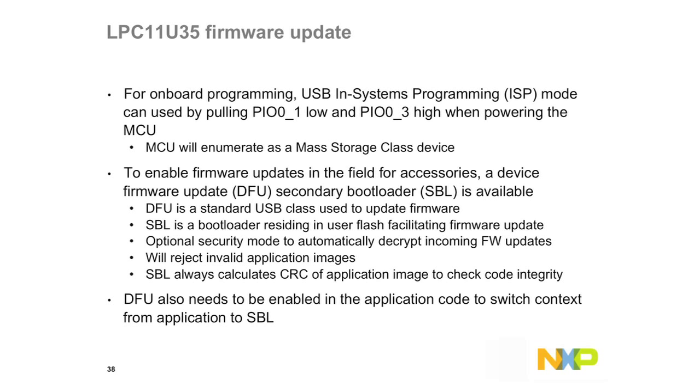And then you can delete the current firmware and drag in the new one, just like you're putting files on a flash drive. But this is not the most customer-facing solution. So NXP also provides a device firmware update secondary bootloader, or DFU SBL. The main points of a DFU SBL are that it resides in user flash, and it provides added security. So if you want to encrypt your firmware before you program it, then the SBL can automatically decrypt it before it programs it to flash. And also, the firmware update will have a section for a CRC checksum for code integrity. Make sure you're not programming a new firmware that's broken.